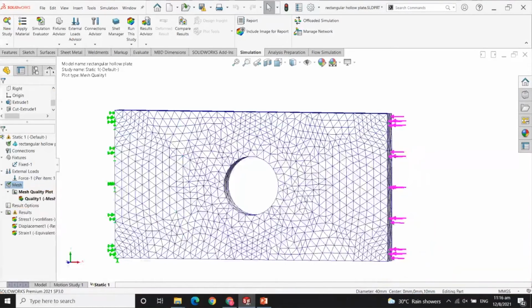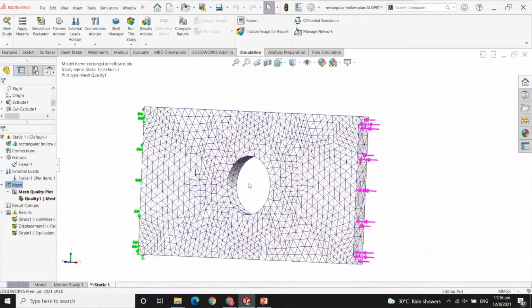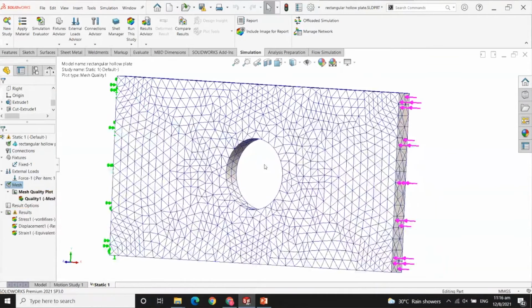if we use the solid element, this one we can use the solid element, then I say that it will take 2 days to finish this simulation, to run this simulation. But it will take only 2 hours to finish this simulation if I use the shell element. Which one should we choose?